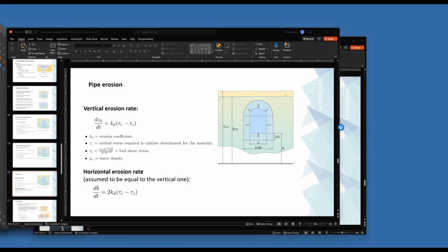Is the model able to simulate open dams like silt or window dams for sediment control in mountain rivers? Yes, it can. It can do that too. You can enter the specific geometry of an open or partially open dam, with bands that can block the flow, and some portions that can let the coarser material pass, and you can model that too, because the flexible mesh allows you to enter those obstacles quite easily.